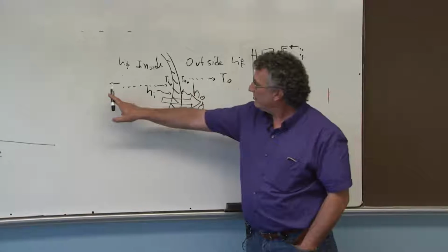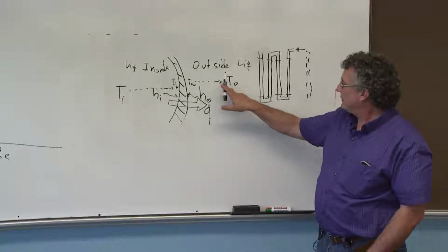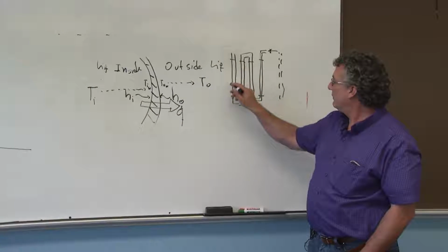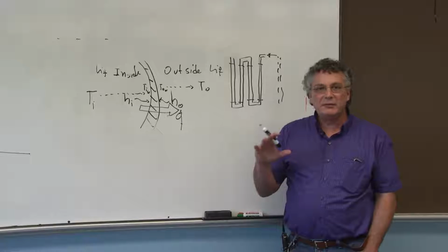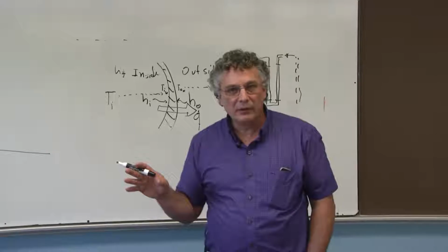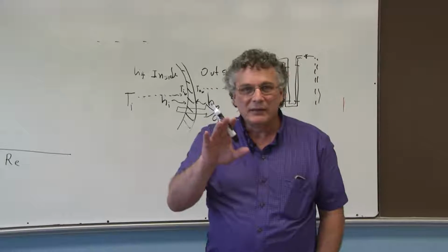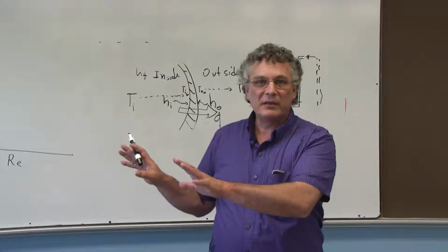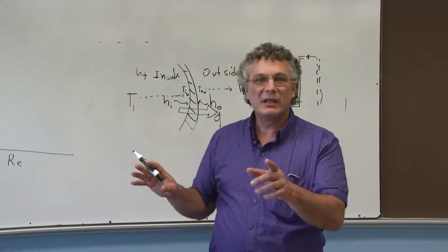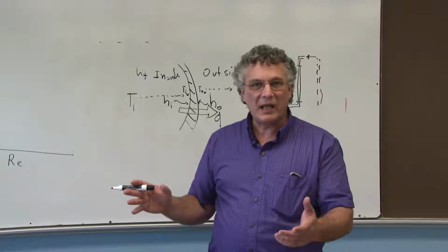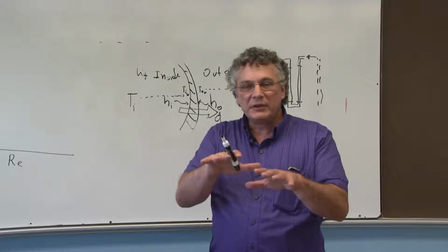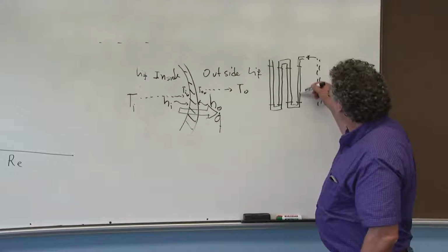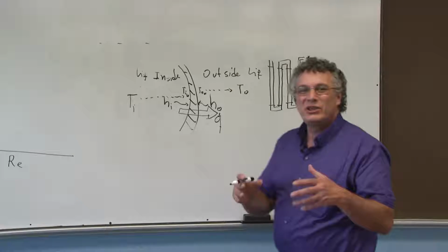Therefore, this internal temperature and this external temperature, the temperature of the fluid going outside, are different at every single point of the pipe, but they stay constant over the whole experiment for a fixed set of flow rates. That's why we call this steady state: although the temperature inside is changing with position in the pipe, it is not changing in time.